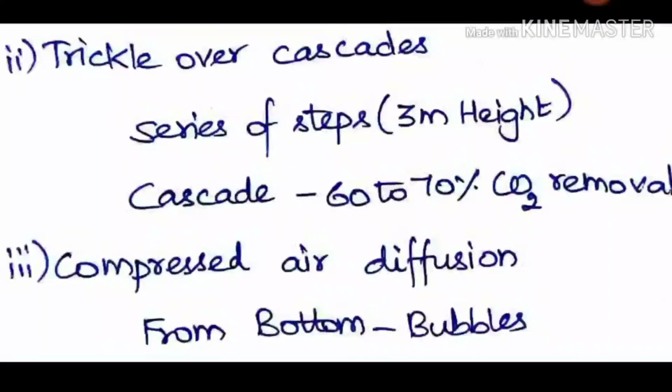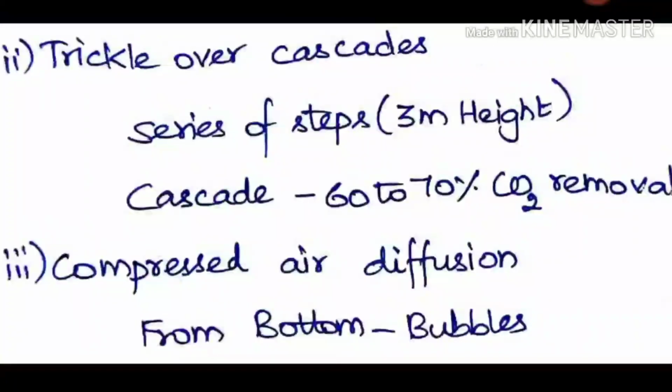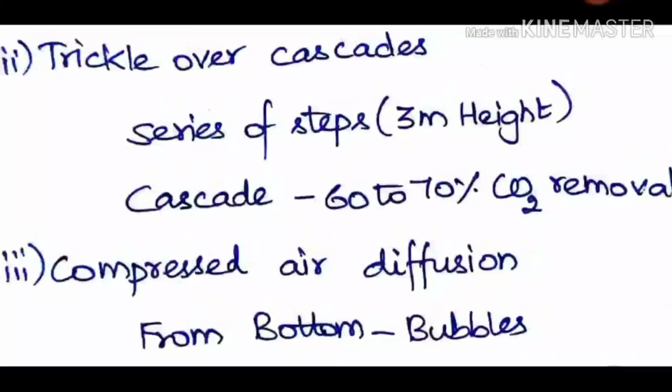So here through the diffused pipes, the compressed air will be released into the water from the bottom, so that from the bottom to top the bubbles will be formed and it will be reacting with the water. So this is also one type of aeration method.